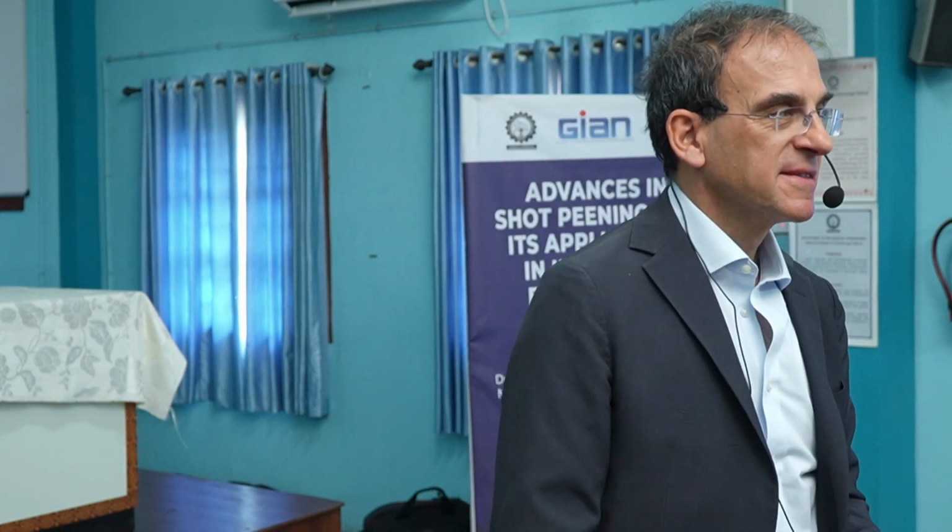No, it's not enough. Indeed there is a slight heating, but not enough to induce microstructural transformation, microstructural change. Even if the exposure time for the shot peening is longer, even then the temperature wouldn't rise. Anyway, you have a flow of air. Whatever the process you're using, air is flowing and is cooling down the system. No, this is negligible.